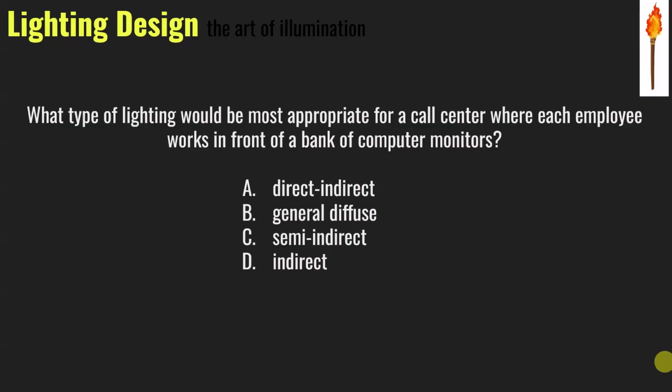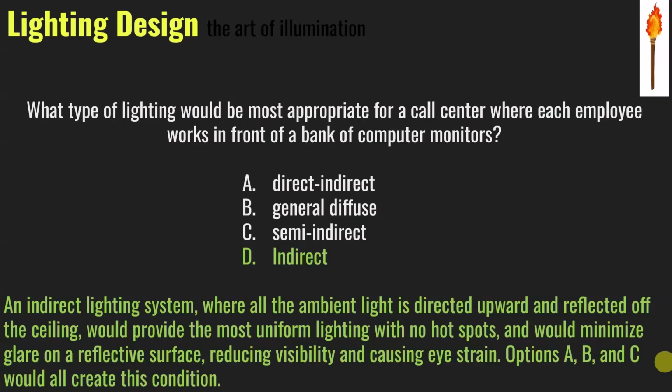I still have some glare issues on this, but indirect, or something kind of like this, but kind of the reverse, where I think this is like a 20-80 distribution. So you have about 20% of the light going up and 80% coming down. I would say the reverse, where you have semi-indirect. So it's mostly going up, but a little coming down on your desk. Yeah, and because this is not a very tall ceiling, these could suspend quite a bit further in a bigger space. Then if we had a little more room to drop it down, it would give a very uniform illuminance. Yes, right.